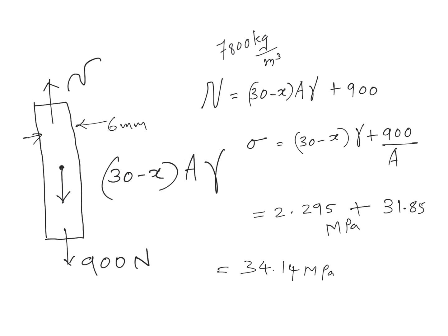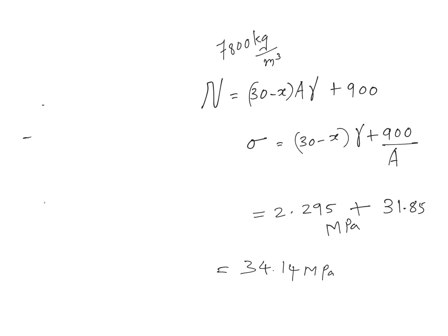They are asking you to compute the maximum stress. So this is the expression of the stress, or the variation of the stress goes like this. Let me draw it once again here. So for that, let me remove this whole thing. See, x is defined from the top of the bar, and for a moment just have a look at that particular expression and come up with an answer at what value of x that expression will assume a maximum value.